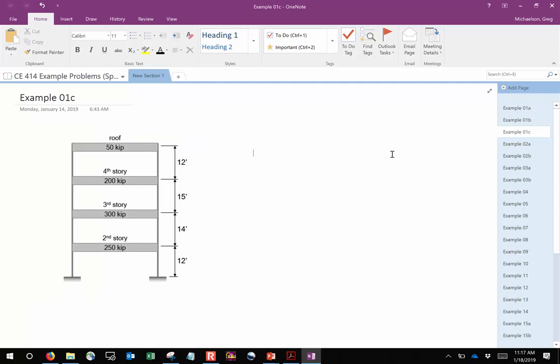Okay, so here's the building that we're looking at, and what we're going to try and do is determine what our seismic force is that needs to be applied at each floor. Because here's the thing. Everybody in here has had structural analysis, and I know that I taught everybody how to use RISA, right? You all could say, okay, here's an element, here's a fixed boundary condition, and you could model this frame pretty easily in RISA, but what you need are loads. You need forces in order to do the analysis. So that's what we're going to try and determine right here.